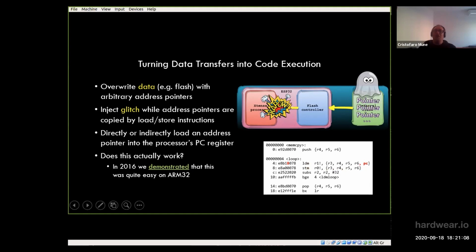But one glitch does not necessarily only skip an instruction. This has been one of the biggest assumptions, I think, in our history of fault injection. A glitch can actually do anything. So in this case, you can imagine that the fault that you have injected is doing something different. It's affecting the opcode of the instruction.